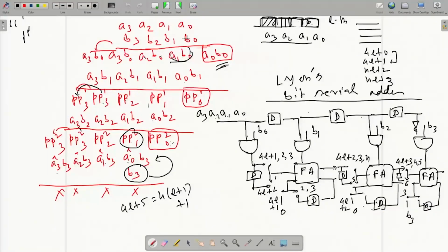Suppose we are doing this multiplication, if say B1 is binary 0, then we know the AND gate result of any bit with B1. If B1 is binary 0, A0 dot 0 is 0, this is 0, this is 0, this is 0, and when you add, no change, you get the same result, which means this entire addition step here can be skipped. So, if you have more and more zeros, these intermediate addition steps can be skipped, which gives rise to a lot of saving in hardware.